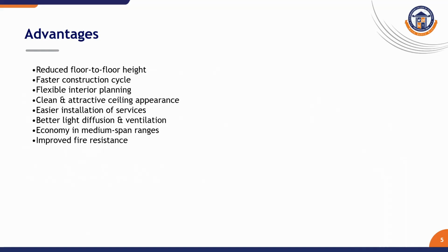It reduces floor to floor height, saving on building height and materials; faster construction cycle due to simpler formwork; flexible interior paneling, as partitions can be placed anywhere; clean and attractive ceiling appearance with no beam projections; easier installation of services such as electrical and plumbing; better light diffusion and ventilation; improved fire resistance due to uniform thickness; and it is economical for a medium span range from 6 to 8 meters.